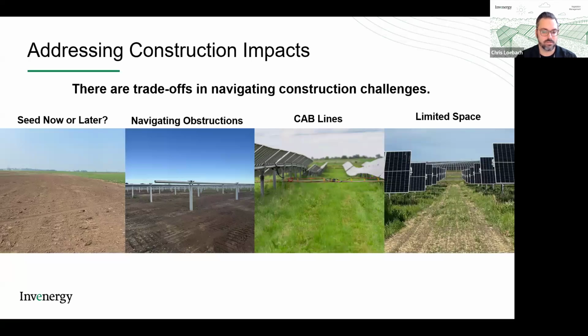And then when you go into the repair phase, you're going to be faced with a lot of trade-offs. There's no real simple slam dunk choice or approach for repairing and doing remedial seeding. For example, the picture I have here of that wide open bare field, that's post grading. Topsoil has been replaced. It's ready to get seeded. Unfortunately, it's summer. So the question is, do you seed with your permanent seed mix when you're outside of a good seeding window? Or do you install a temporary seed mix now, come back in the fall and put in your permanent seed mix? Restoration perspective says the latter choice.